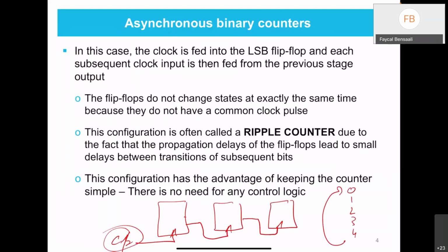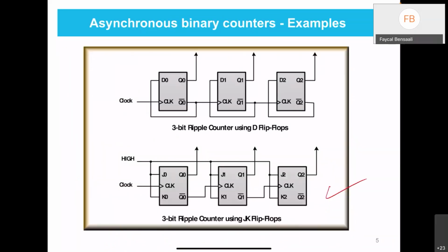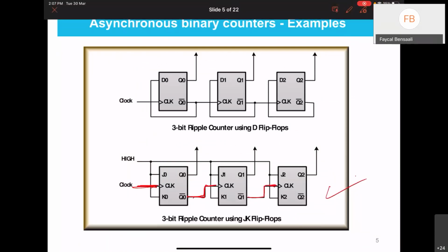You just take flip-flops and you clock them this way. You know, the same circuit that I showed you in the previous tutorial. I mean, we gave you the circuit, and when we drew the waveforms, we found out that it's a counter, right? So this was the circuit, if you remember, using JK flip-flops. I can do the same using the flip-flops. So this is exactly the same circuit that we did. As you can see, this is the first clock, and then we take the next clock. So this is a 3-bit counter. So this counts from 0 to 8, to 7, sorry.